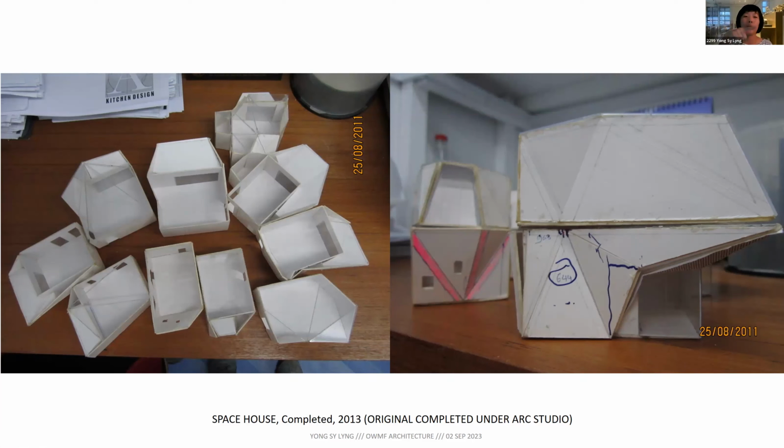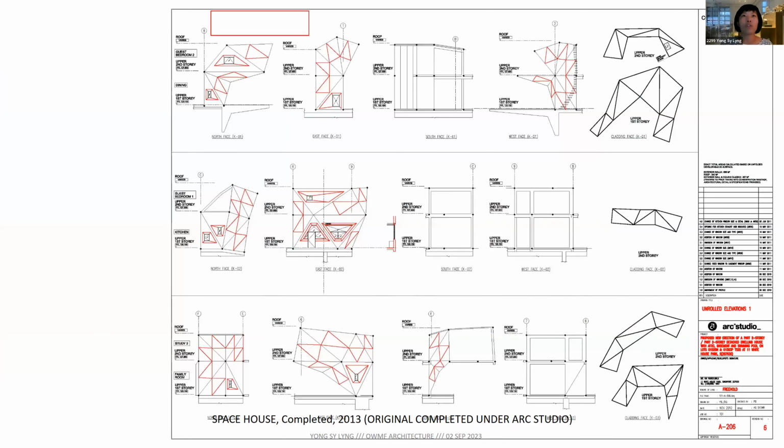So from here, usually we just issue plans and sections to the engineer, but this time we have to issue a set of models like that to the engineer as well to study, so that they can also model in their structural software, right? So eventually the engineer came up with drawings like this, and you can see that again we can describe every point accurately, right? And then these red lines eventually form our plastering groove lines so that the plaster doesn't crack, right? The red lines are a subdivision of the bigger triangles in black lines.